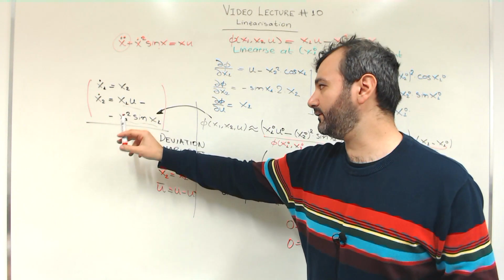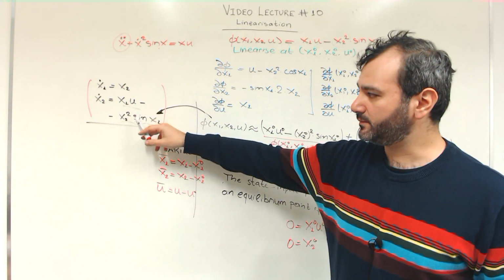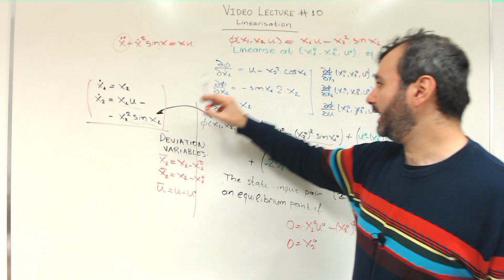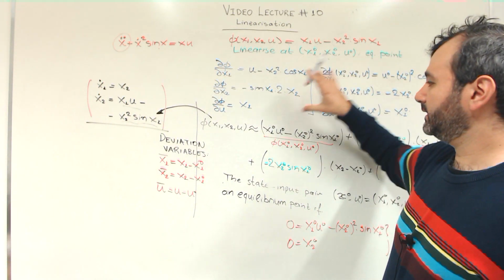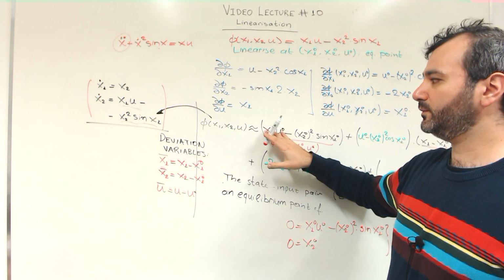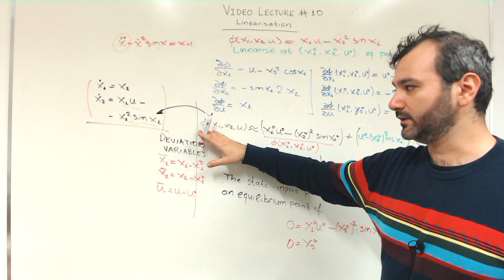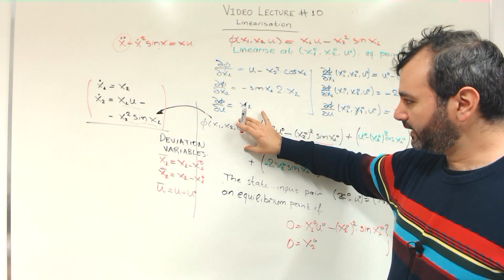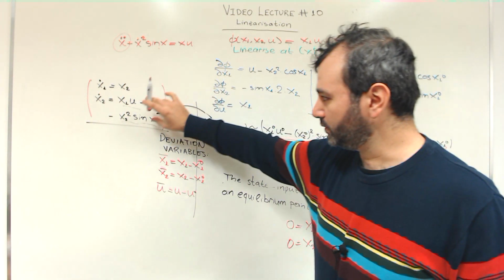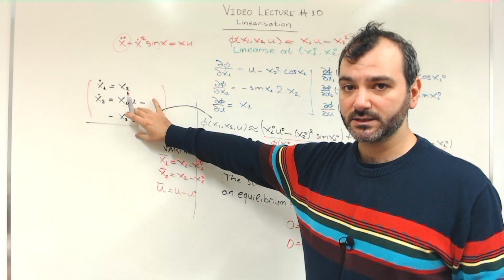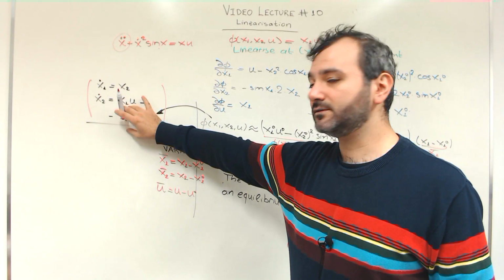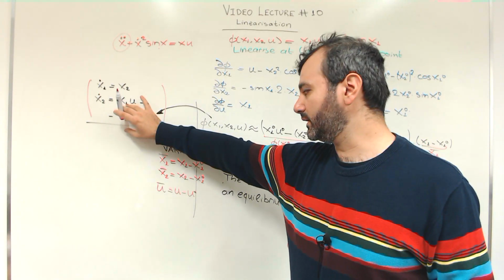We defined a function phi that describes these nonlinearities, and we approximated it using Taylor's approximation theorem for functions of several variables. So this is it. And then what you need to do is to plug this into your state space representation and have a linearized version of your nonlinear equations.